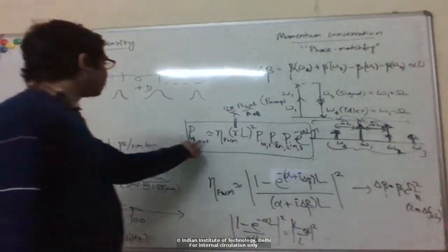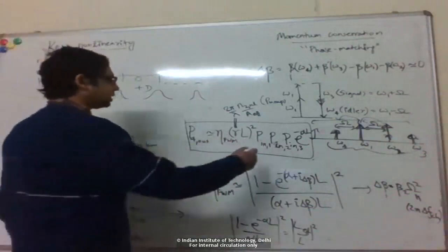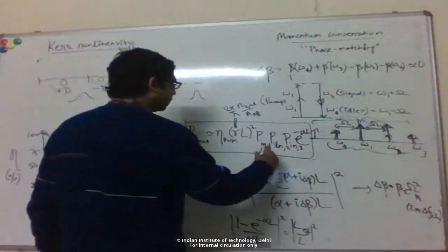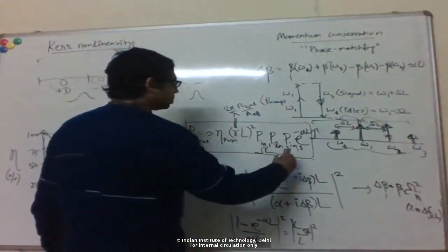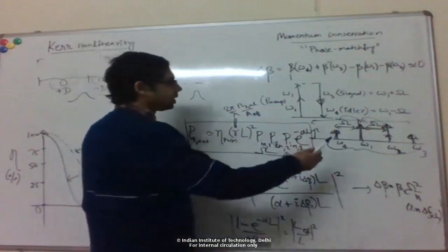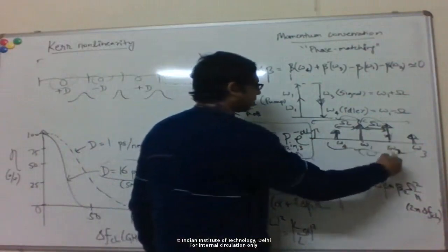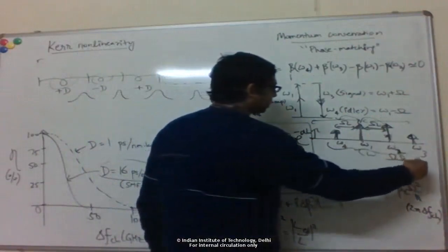So you can see in four-wave mixing, you can do that straightforwardly. I have some data, let's say in channel 1 here. I just use a continuous wave laser. I can even do degenerate, for example. So I just need one continuous wave laser and another wavelength which has my data on it.